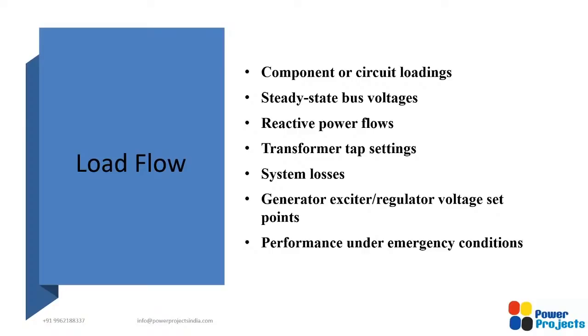And performance under emergency conditions, that is, contingency conditions which I have talked about, n-1, n-2, etc. Where your power flow will be different, your voltage will be different, losses will be different. So your system may go out of control. So all these things you can check in the load flow analysis.